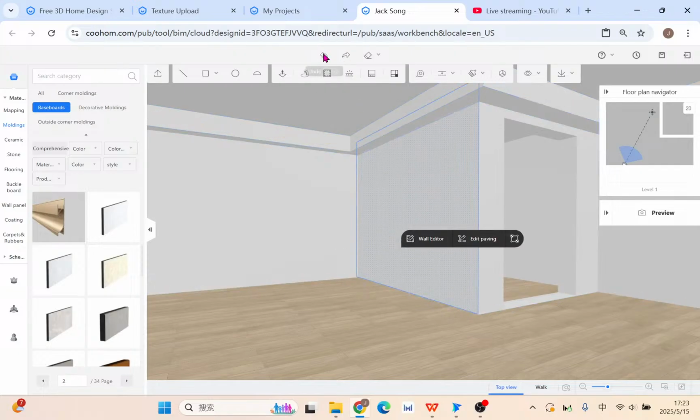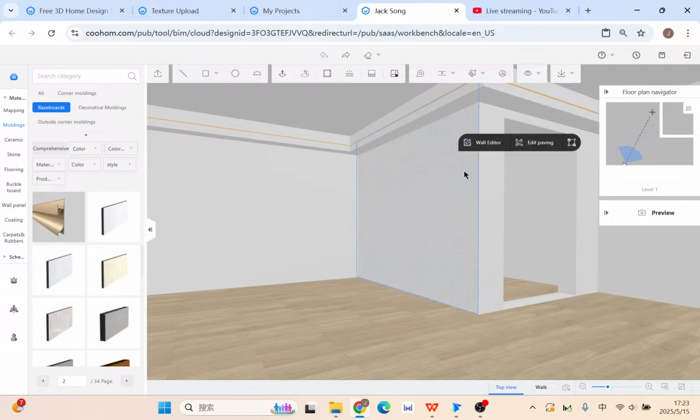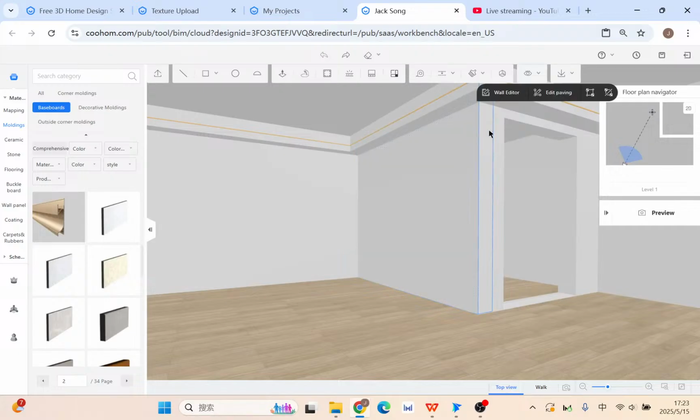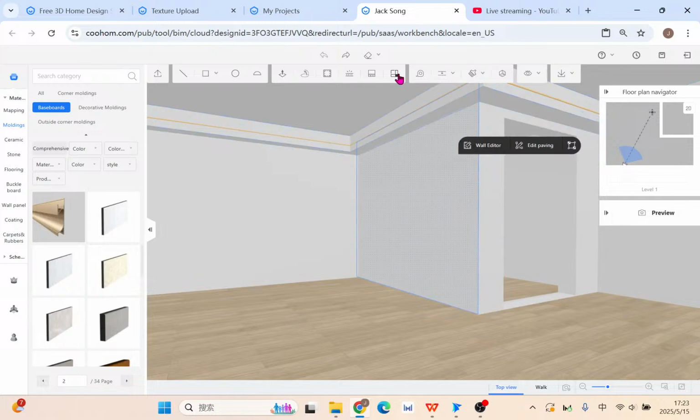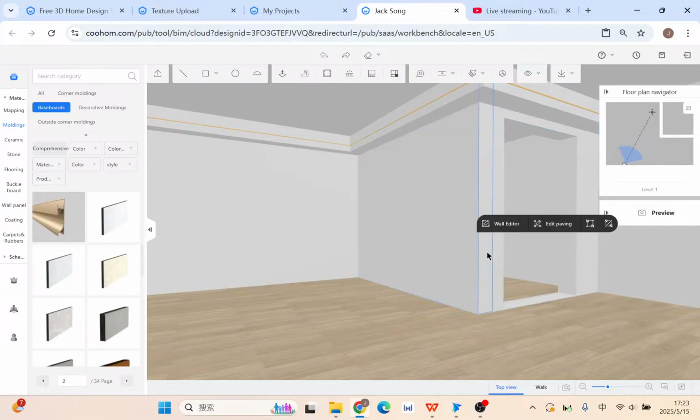Okay, of course, before that, wall extrusion, you can either draw or you just settle with the walls. Okay, but just pay attention about this 19-degree angle. This angle you don't have to worry about, but this angle you need to use the closed corner. Okay, to close and end these two areas to get it closed, because you set extrusion here, you set extrusion here, then it will have a 19-degree corner gap. Then you need to use this one to create the closed corner. Okay,